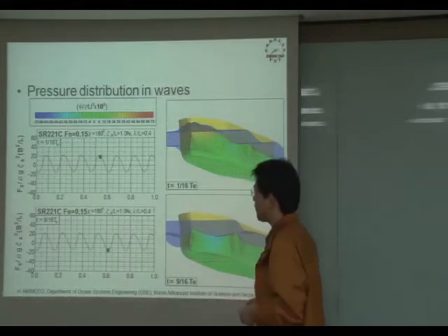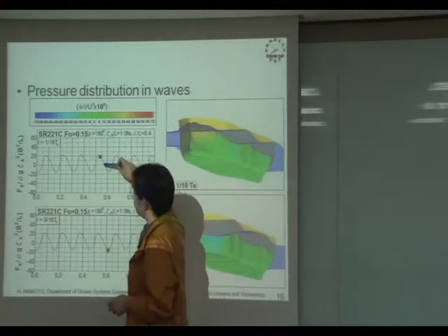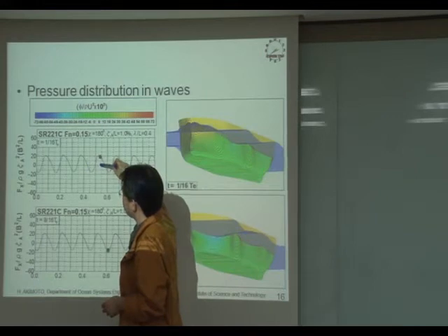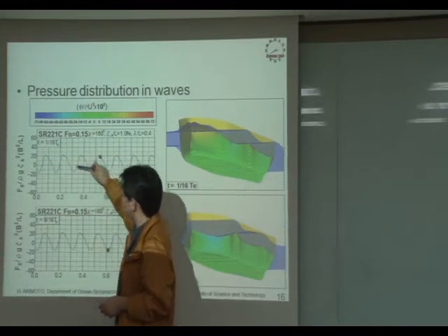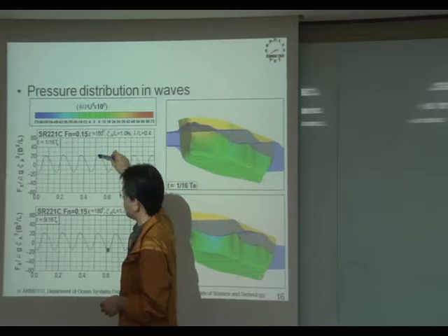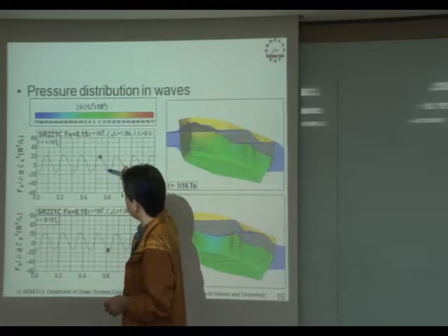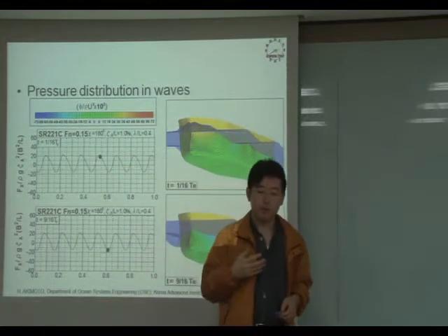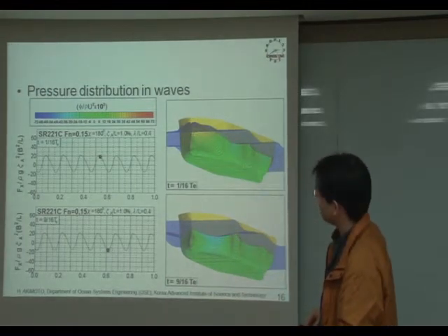One important thing is, if you look at this time history closely, in some cases, this is the zero line. So at this point, drag is positive, but at this point, the total drag is negative. It indicates the wave pushes the ship in the forward direction.